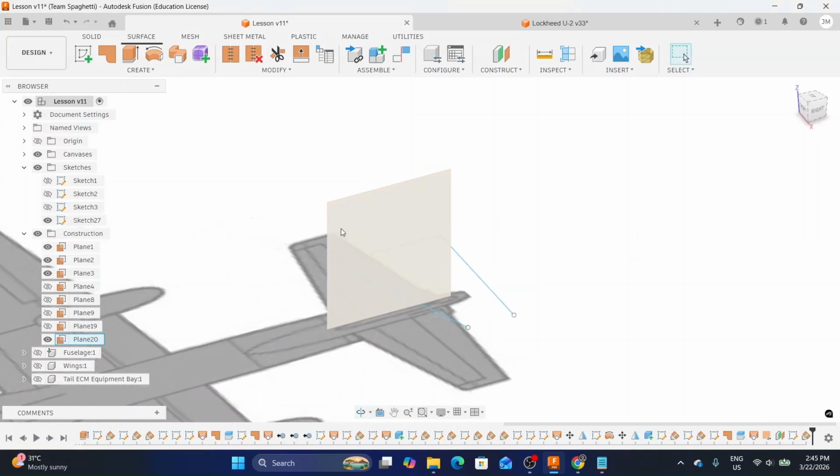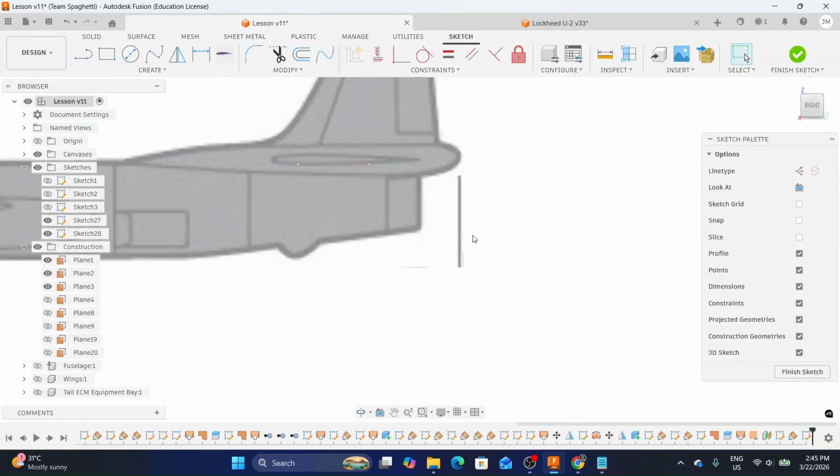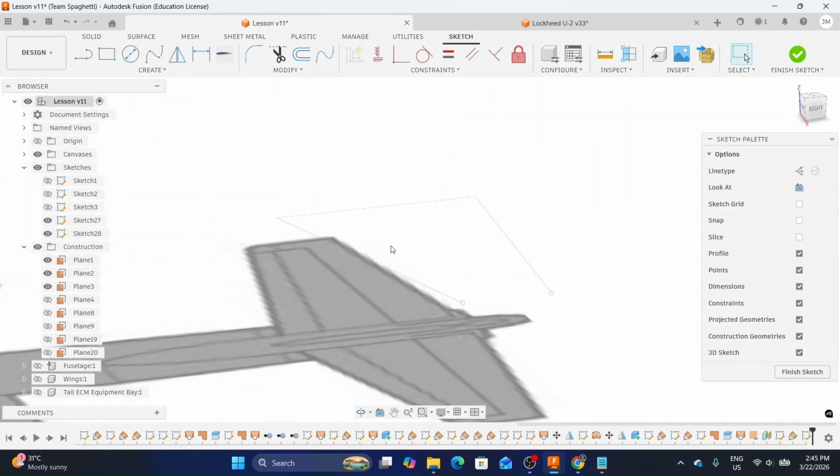And now we will be creating a sketch from this plane. So I'll select this plane right here, create a sketch. Let me just rotate the view, and then I'll project this line right here. So press B on my keyboard. Since this is a 2D sketch, let's switch the selection filter only to specified entities, and then select this line right here. Press OK once you are done.